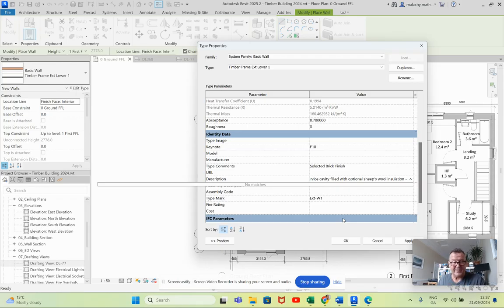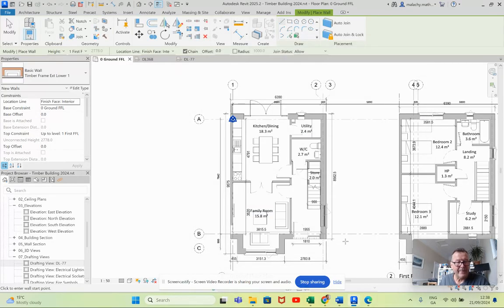Once you have them on the Excel spreadsheet, you can use these notes in different projects, if you're building new wall types or whatever. So what I want you guys to do is, when you create a new wall type, a new floor type, a new roof type, or anything else like that, fill out these boxes as well, will you please? The description, that is your main construction description. Give it a type mark and fill out the type comments here as well at a minimum.